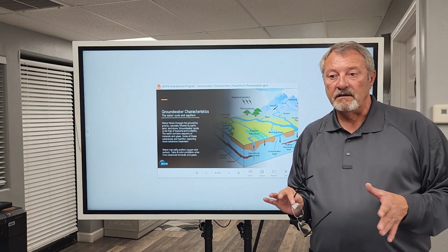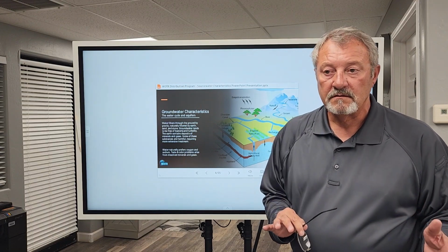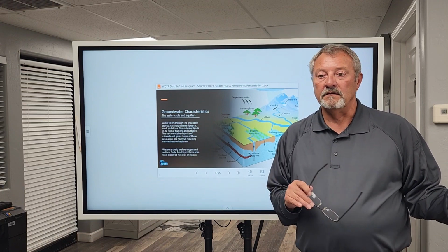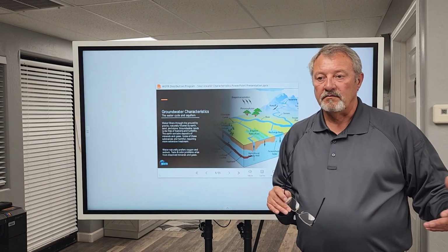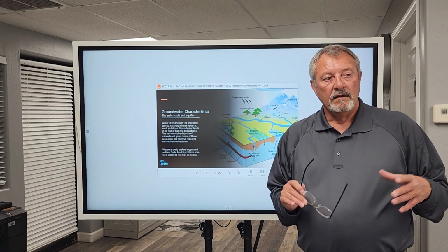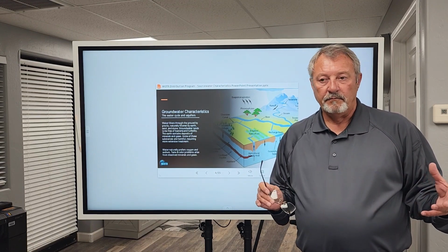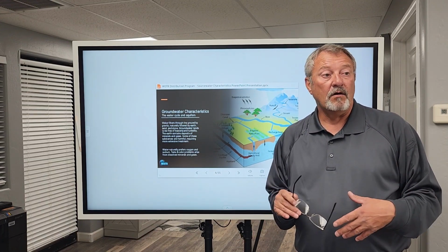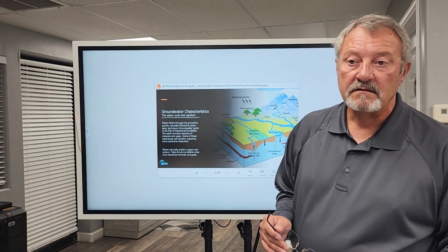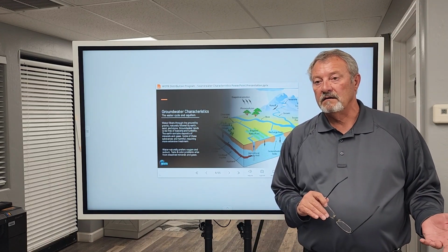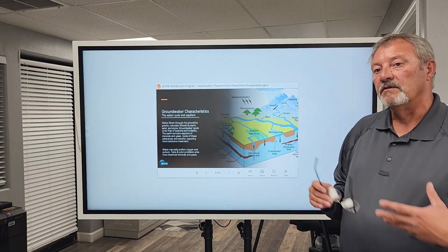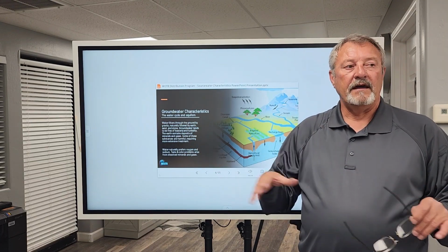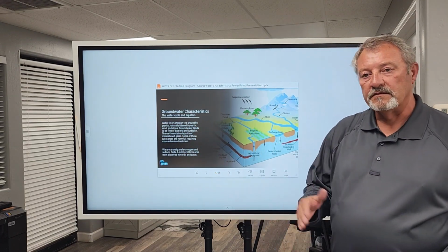However, what groundwater does encounter are pockets of minerals. They may even be radioactive. You've heard of uranium and other material that is mined in different parts of the country because it's radioactive. So the water might encounter radioactive pockets of minerals, calcium, magnesium, and other minerals that are in the water. It might also encounter pockets of natural gas, hydrogen sulfide, carbon dioxide, and it picks those things up. It picks up those characteristics, right? You combine all that and you get the characteristics of the water, surface water versus groundwater.